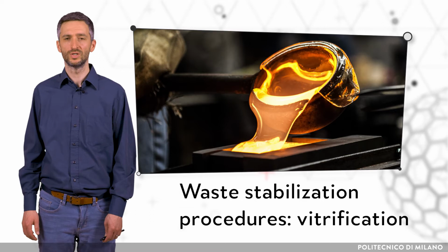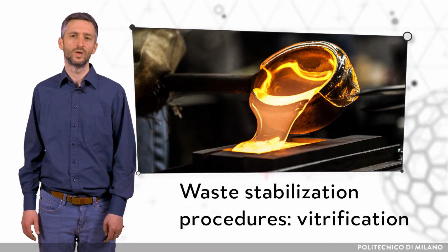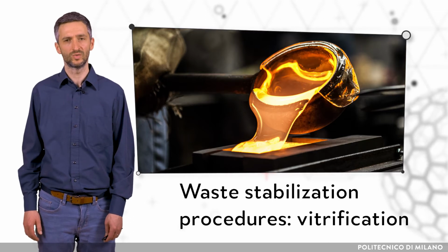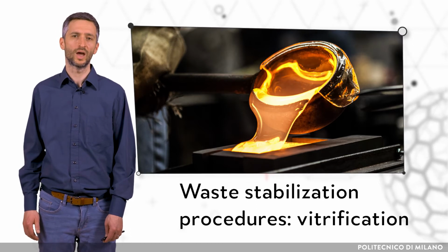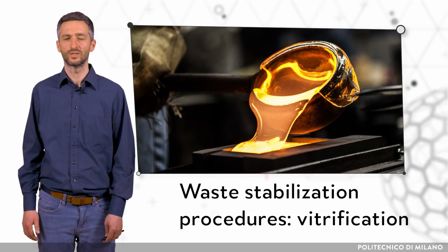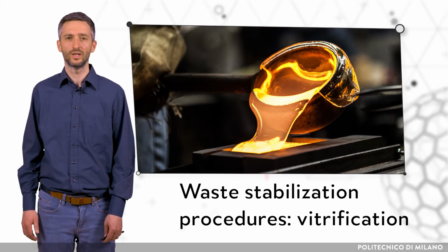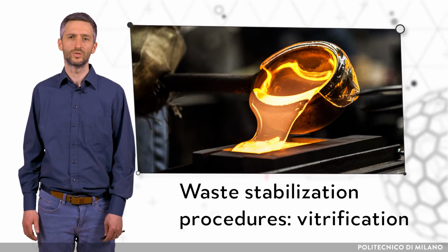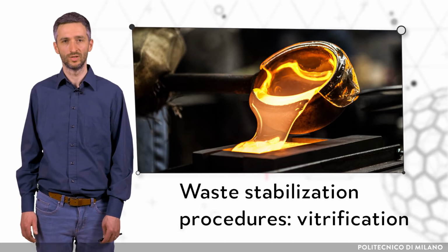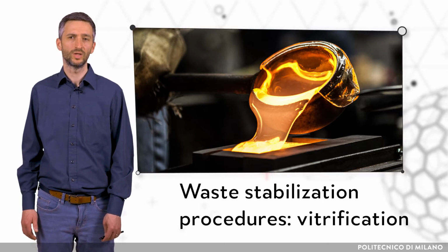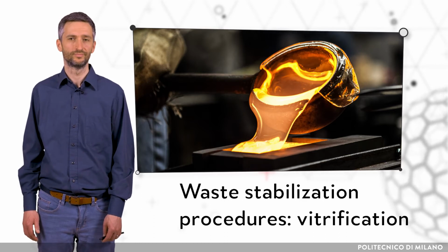Vitrification is one of the most suitable waste stabilization procedures for aqueous radioactive wastes, which should be solidified before safe disposal. Vitrification is a process of forming glass at high temperature from a mixture of wastes and additives. Glass is an amorphous material which is highly chemically resistant, which allows it to remain stable in corrosive environments for thousands or even millions of years. Incorporating wastes into glass ensures a high degree of environmental protection.